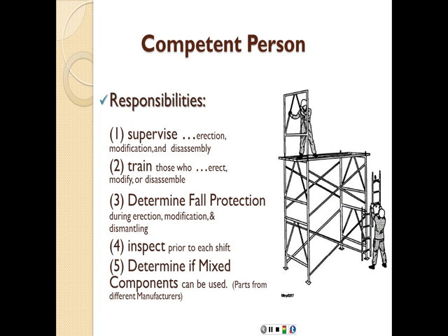The responsibilities of the competent persons are going to include the supervision of the erection, modification, or disassembly of the scaffold, training those who are going to do the same thing, who are going to erect, modify, or disassemble the scaffold, determine what kind of fall protection measures should be taken during erection, modification, and dismantling, inspecting the platform or the scaffold prior to each shift, because again, if there have been some heavy rain, for example, which have made the soil softer, now it can destabilize that scaffold. Or if you have placed too much material, bricks or blocks or whatever, and again that may make it weaker